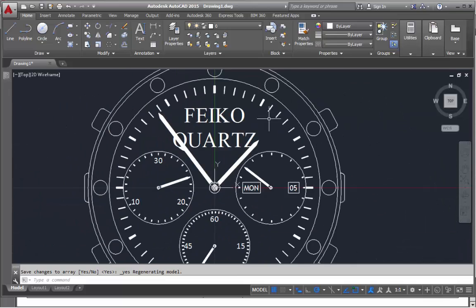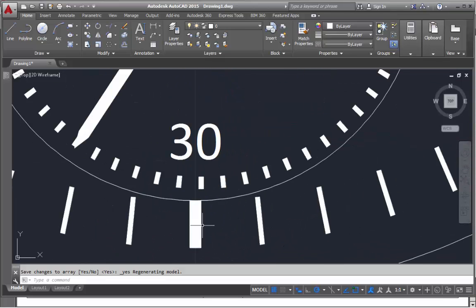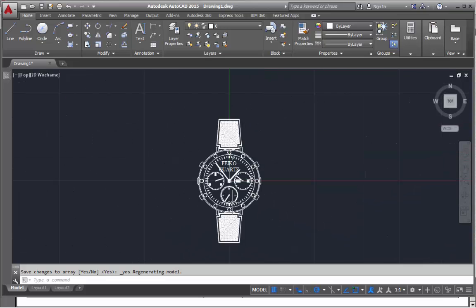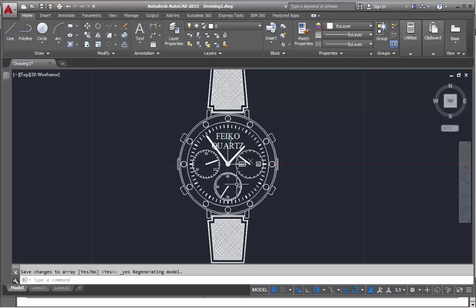So what we're doing is it's pretty much like a component in SketchUp where they make a change to one thing and everything else updates. So it's a nice sort of elegant way of finishing off the hatching. And that's it as far as the drafting goes. There's one more thing that we need to do, and that's put it into paper space. So we're going to move from model to one of the layouts. We'll arrange it in two different viewports, two different scales, and then we'll set it up so we can print it to the machines in the university.